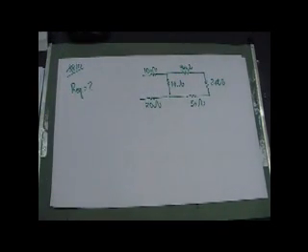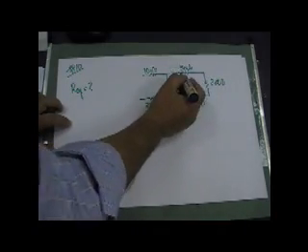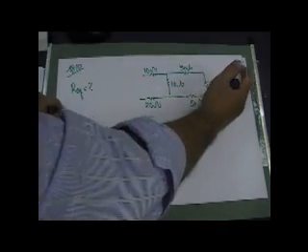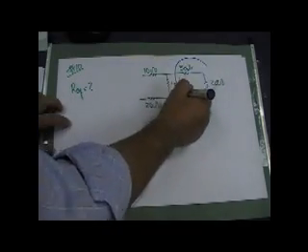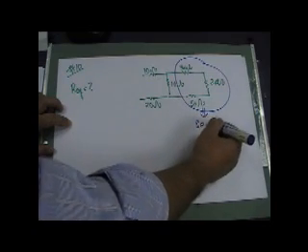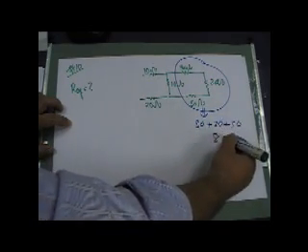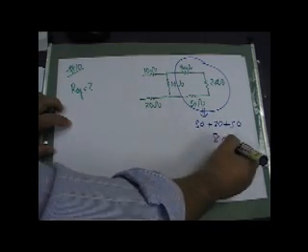Question number 10 asks, what is the equivalent resistance of the network shown? Again, we have to be careful with this because they said there will be questions like this in the exam. So let me start from the far end, and then go this way. I combine these as series, so this will give me 30 plus 20 plus 30, so 60 plus, that's 80. Right? And then this 80 ohms.